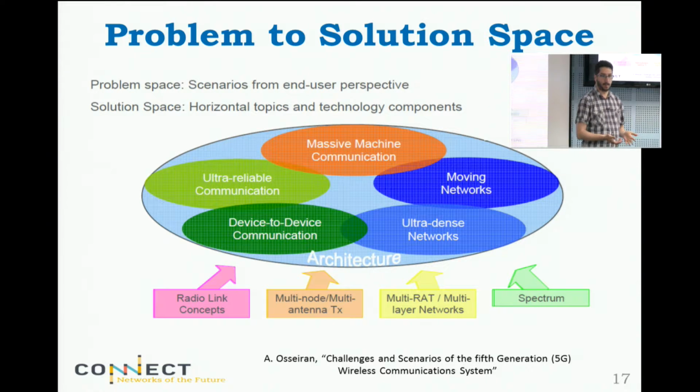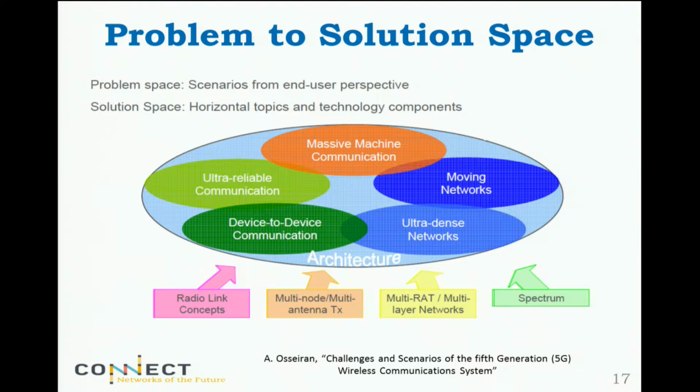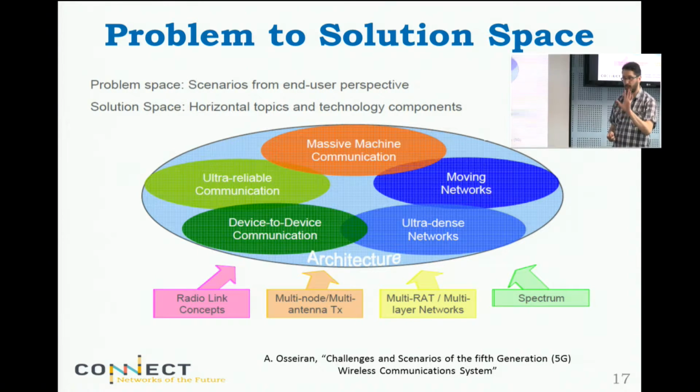Another thing is physics, okay? So there is a need to basically position antennas on a device with a certain distance, okay? So this distance is roughly given by half the wavelength. So the wavelength actually, as you know, is given by the speed of light divided by the carrier frequency, right? So the higher you go in frequency, the smaller your wavelengths become. And so potentially, I'm not saying it's always true, but potentially you can squeeze more antennas.